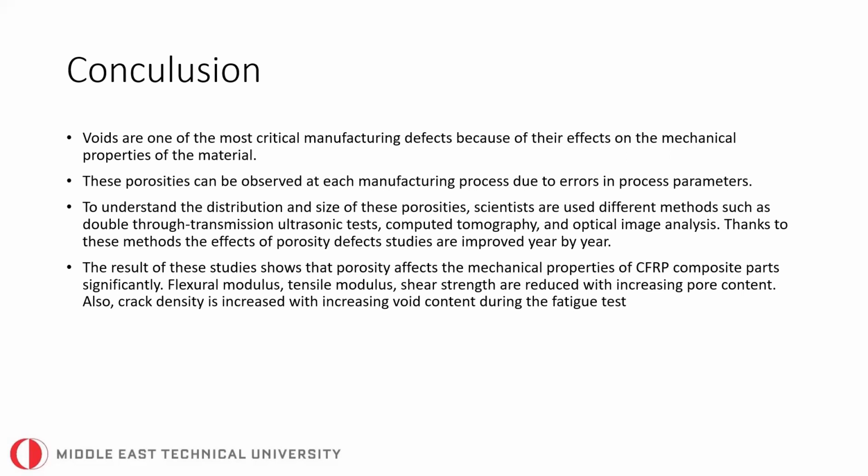Thanks to these methods, studies on the effects of porosity defects are improving year by year. The results of these studies show that porosity affects the mechanical properties of carbon fiber reinforced polymer composite parts significantly. Flexural modulus, tensile modulus, and shear strength are reduced with increasing pore content. Also, crack density is increased with increasing void content during the fatigue test.